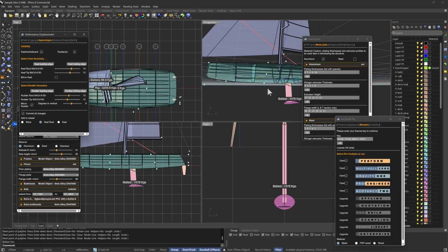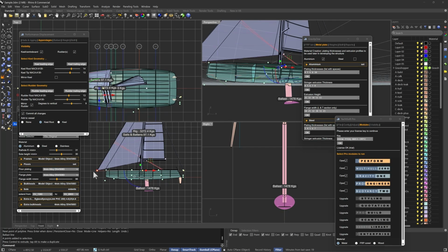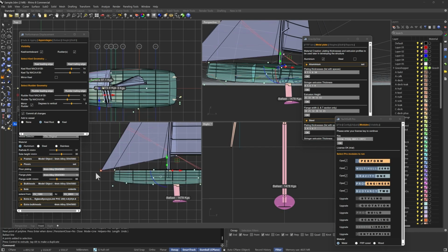So the rig needs to be manipulated. It sort of starts off with a pretty basic rig, and you do have to line all the points up so that you've got realistic rigs. This is very useful to get weights out. It'll actually calculate the weight of the rig with the sails up, and you can then check your heeling moments, things like this. So I'm just going to, we don't need a bowsprit on this boat. Oh, we do, but hey.